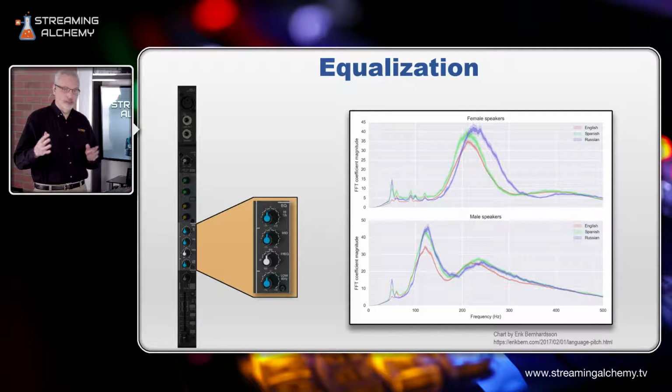Typically, the frequency bands that will impact voice are somewhere between 500 hertz and 3000 hertz. If you want to make adjustments in the midtones with a parametric EQ, that's probably where you try to dial in to find the right midpoint and make your vocal adjustments.